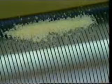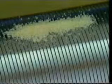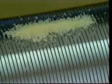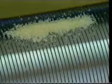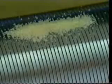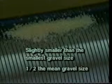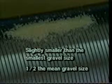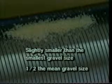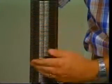Selection of a screen should be made with the primary aim of preventing the gravel pack material from flowing through the screen. Two common methods of determining screen openings, which yield approximately the same results, are to size the openings either slightly smaller than the smallest gravel size or 1/2 the mean gravel size. Pressure loss through the screen is generally minimal, provided the screen is not plugged with fines. The correct placement of a screen of proper length, diameter, and composition is essential.